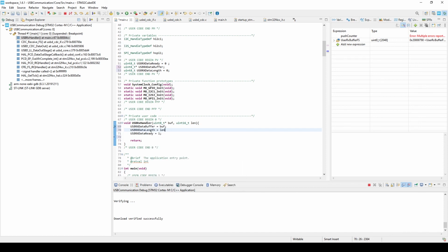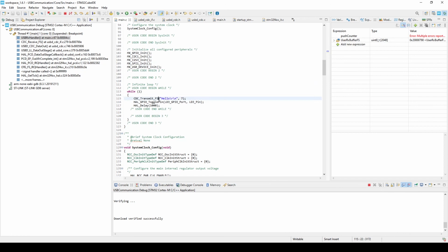You take the important information, and that's it. You don't need to return, you just finish the function. This helps the microcontroller end the process of handling the interrupt and move forward from the interrupt. But then later in your code, let's say here, I just remove the hello for now.